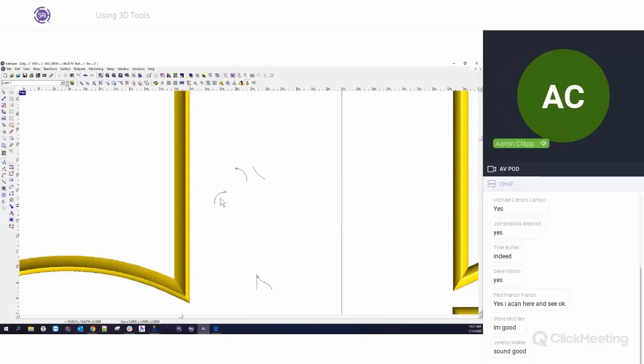So again, if you find that you're having some issues with this, try changing one thing at a time. The worst thing you can do is to try changing too many things, and then you don't know what really fixed it or what really caused the problem. So what I did in this case was I did two things. The first thing was I changed the direction of the contour. If you go to transform and say reverse open contours, this will reverse the contour to go the other direction. So now you can see that it's going the opposite direction.